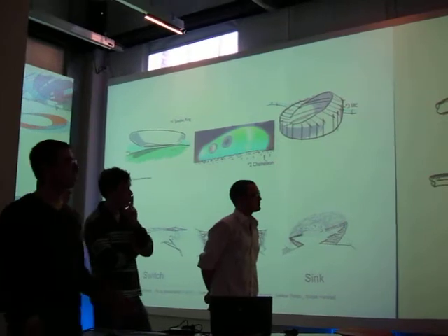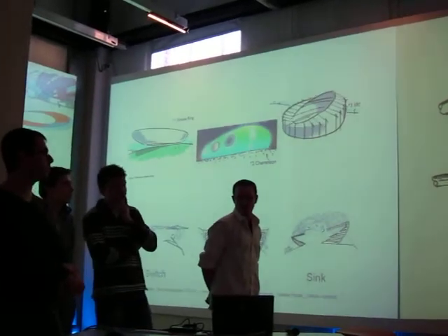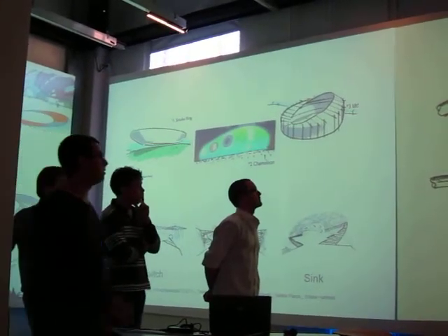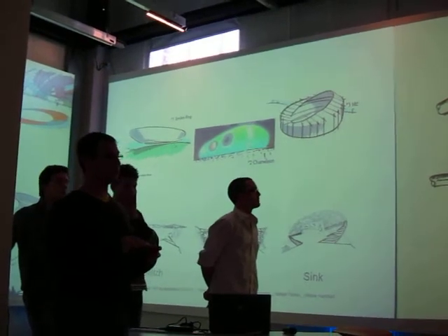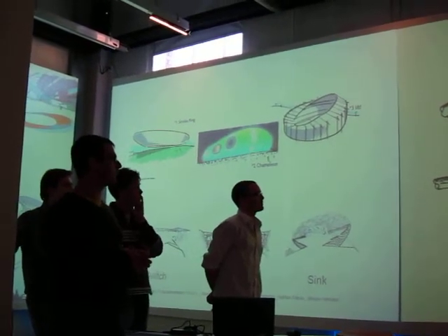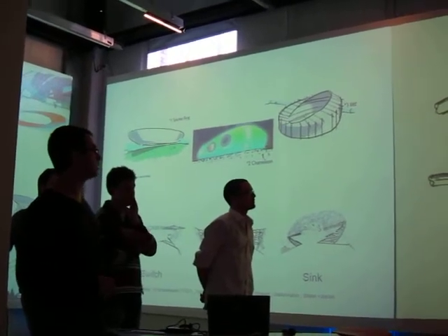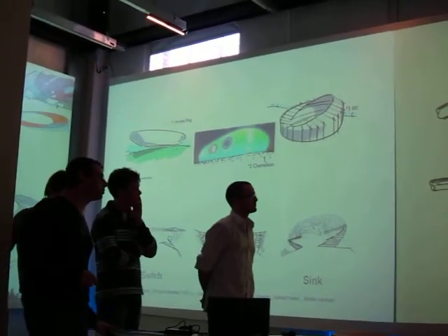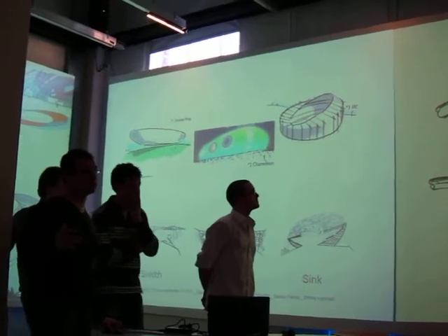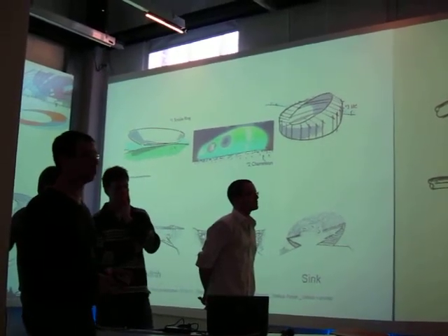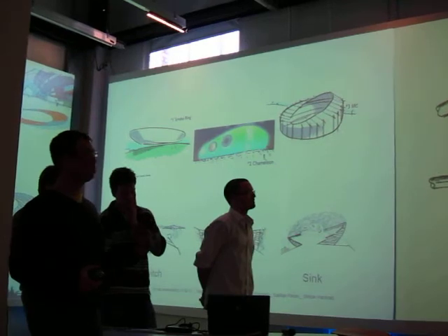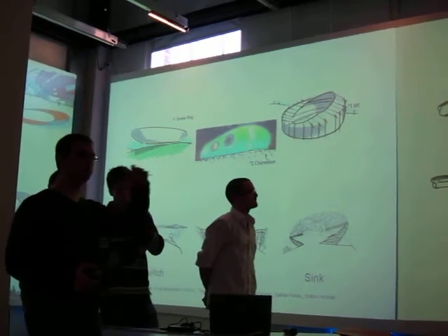The last system of that detail is what we call the Sigma, which we thought of in order to get a very, very large amount of expansion. This system can expand to 400% of its initial length, and that's a concern to us because we have huge differences in geometry over the stadium.